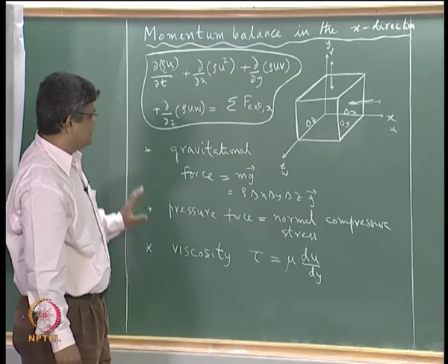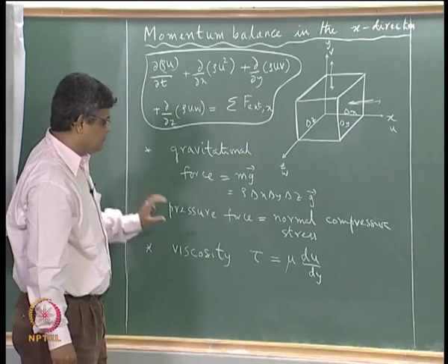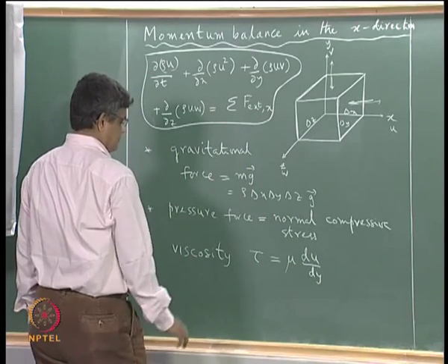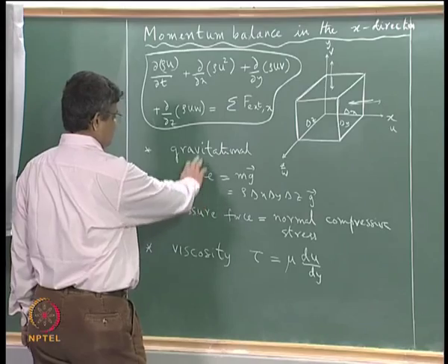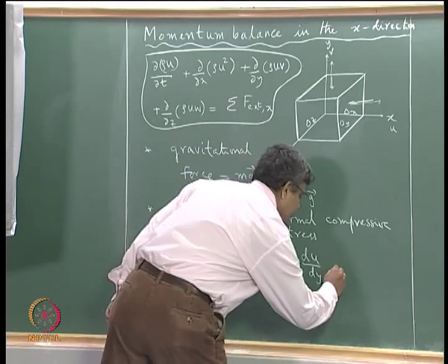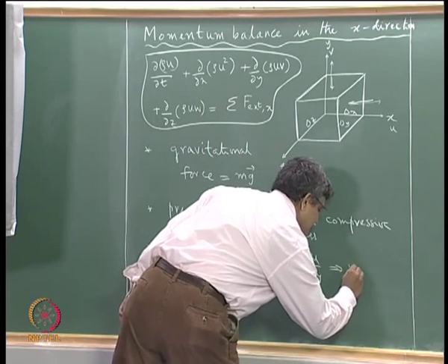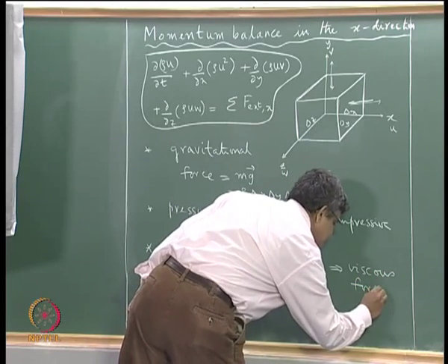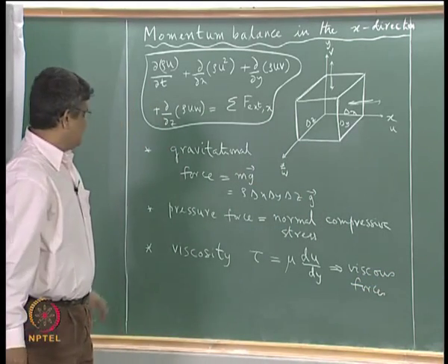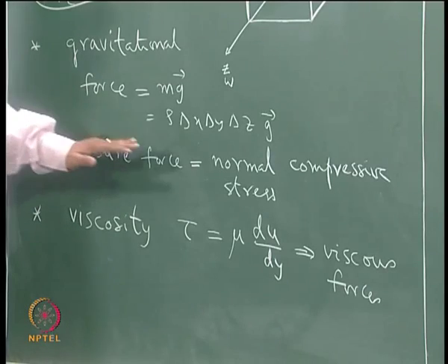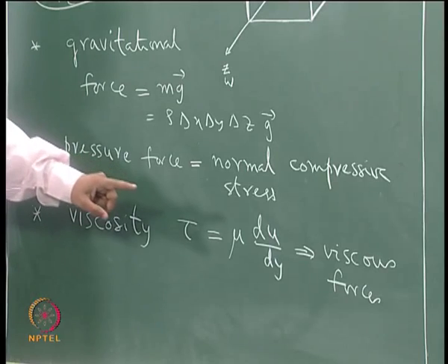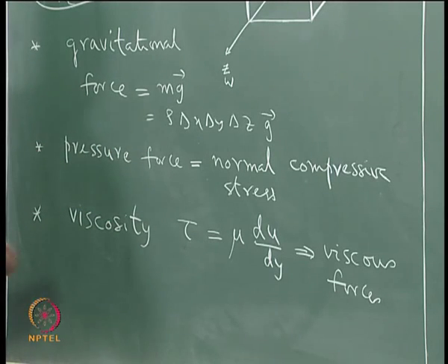So one can say that a fluid will have viscous forces in addition to the pressure force and gravitational force. So we have as the third element viscous forces. Just like pressure forces are normal compressive stresses acting on the surface, viscous forces are also arising from viscous stress.